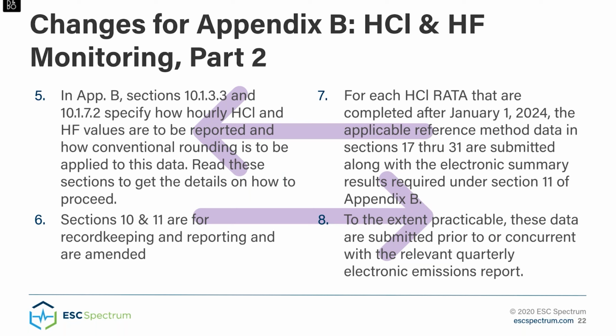For HCl and HF monitors, on this slide you can see that a lot of the reference method data that are collected and used for your reporting is going to be reported using sections 17 through 31 of Appendix E again. So you need to review Appendix B and then review Appendix E so that you understand what your data reporting requirements are.